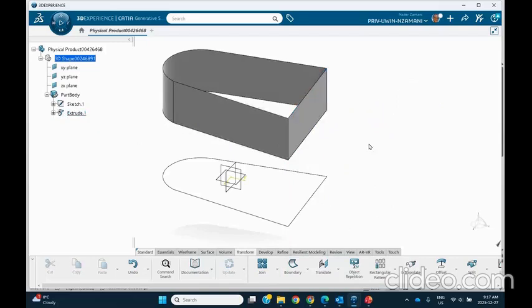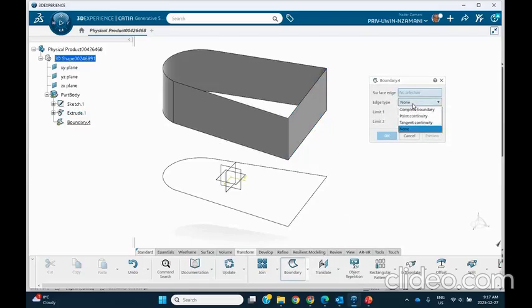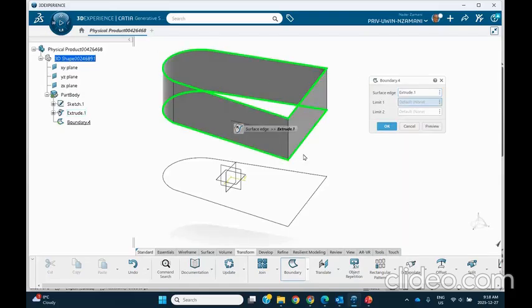All right. Now, click on boundary again. This time say point continuity. We already did the none, then the complete boundary, and point continuity. Select the surface. It takes all the boundaries. And point continuity means that if I select a point here,